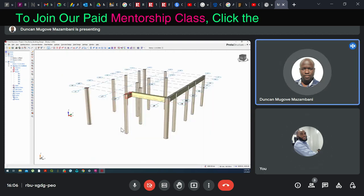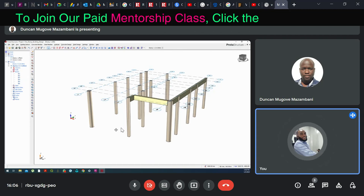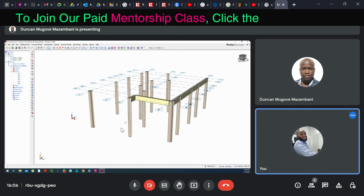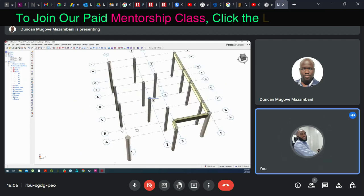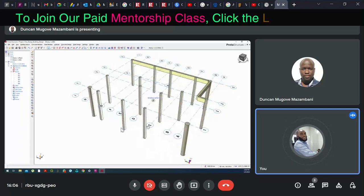Okay, so I need to delete this one. Can you rotate here? To rotate, hold down your right click and rotate your mouse. Yeah, that's fine. So you can see that it's acting like a cantilever beam, which is not okay. So go back, delete that beam, and make it lap to support itself on the other column.